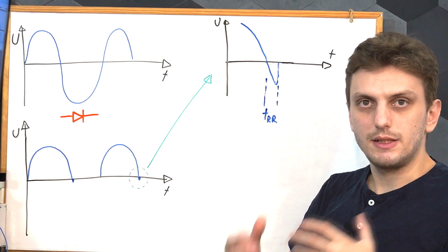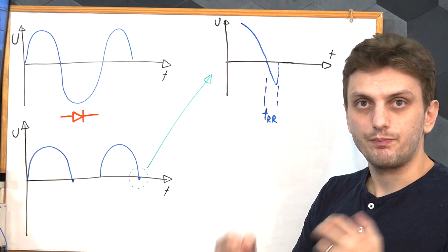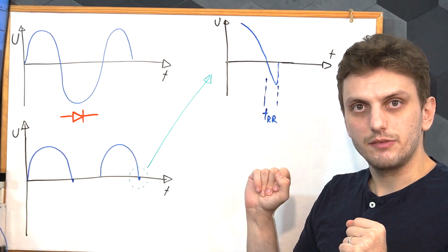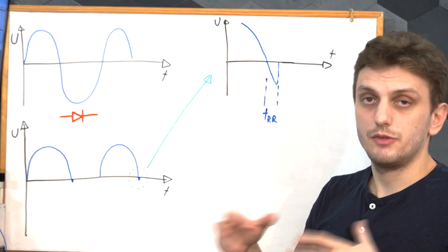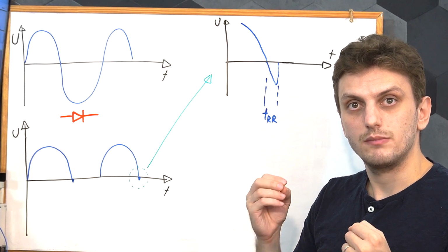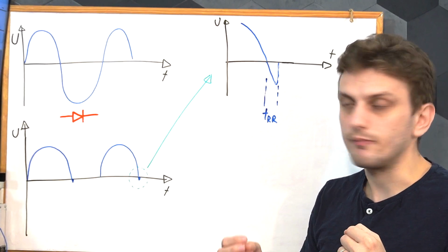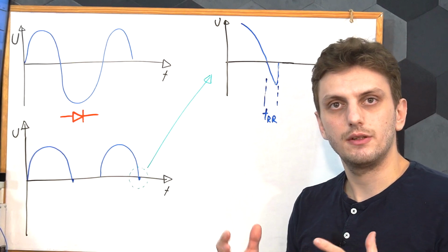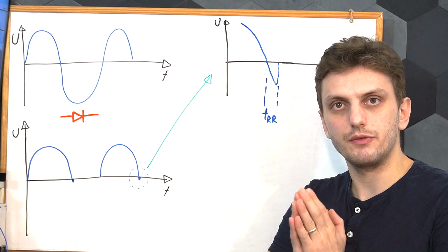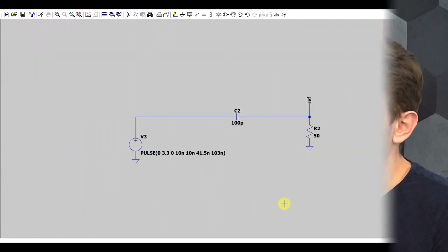So for low capacity radio frequency diodes, you can get very sharp transitions by taking advantage of this effect. And if you want really fast transition times, you have special step recovery type diodes. And this is exactly the effect that you need to get your comb generator to have a very broad spectra.